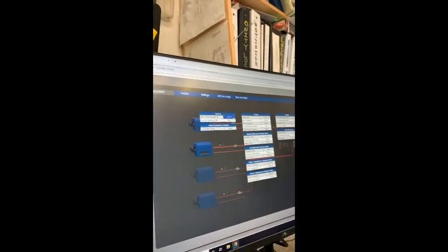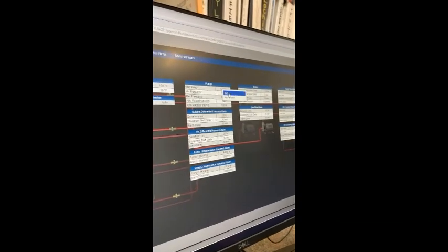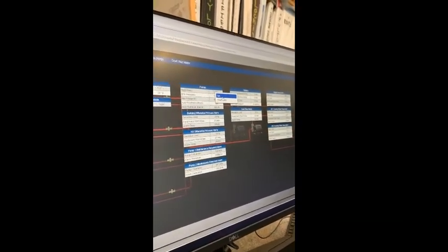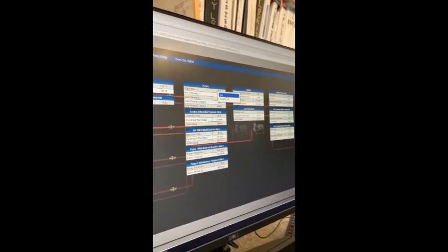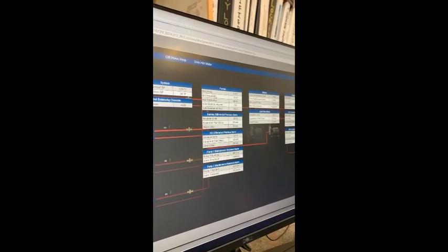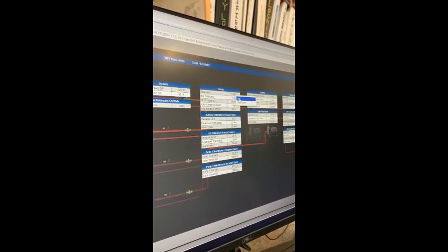I did just want to show you an example. You can see right here, there is a set. A set is if a point does not have anything writing into it, and it's just a value that goes out into the code. Like this is the stop delay for the pumps. We would set that. That's not overriding.